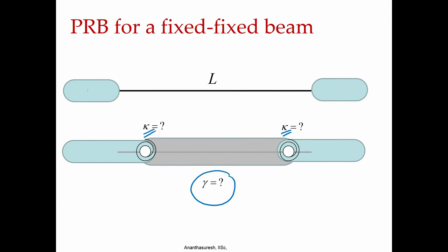So, when these are rigid body connected to other things, at this end there will be transverse force, axial force and moment, and here also there will be axial force, transverse force and moment. They need not be the same, they can be whatever loads that you have, depending on where these two are connected. So, you can certainly model like this, but getting the parameters that hold good for large displacements or deformations of the fixed beam is a little bit difficult.